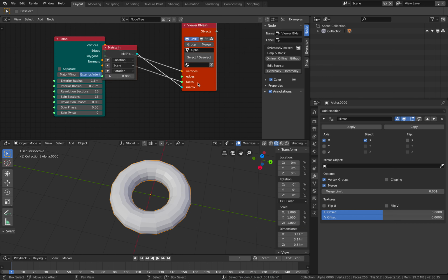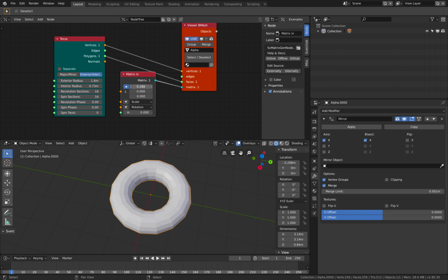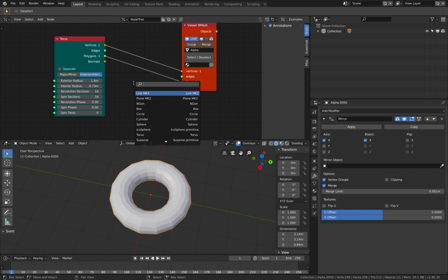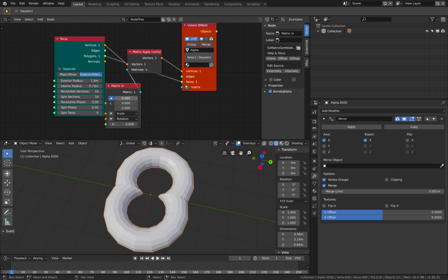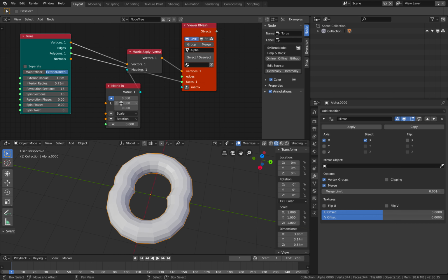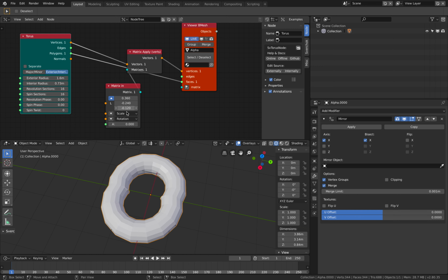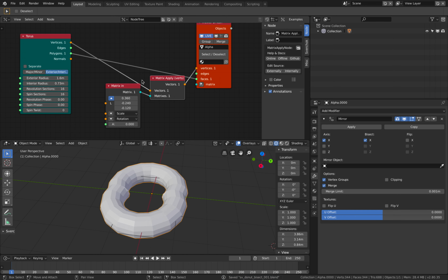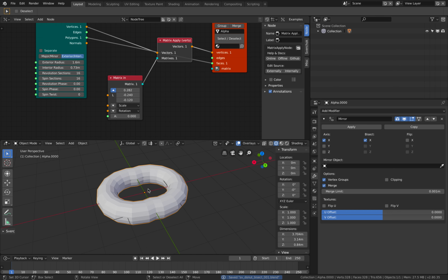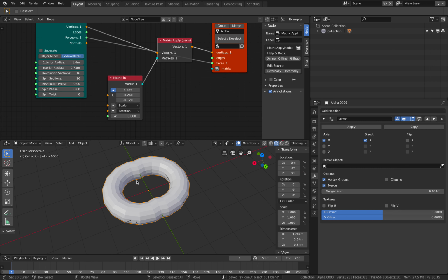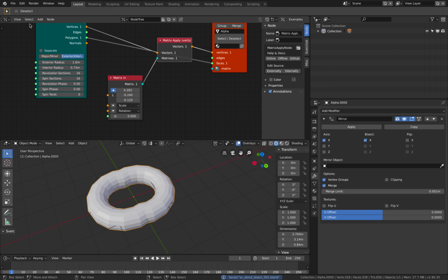If you're thinking you're gonna use the matrix, that's actually not the right way, because this is kind of like moving the objects. So use the apply matrices, and this should be doing what we want. This is kind of like doing it in edit mode and applying it on the fly. It's really, really powerful. So look at the mirror. We are currently doing it in x-axis. So x, and then look at this wheel. So it is correct with the axis.